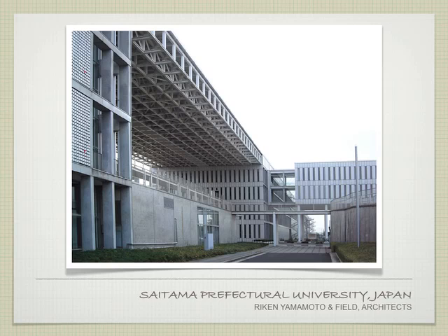right? Worcester Hall in Berkeley, the architecture building, which everybody thinks is ugly, is entirely made of precast elements like this would be. It's almost right on top of the Hayward Fault, so we have those same issues of how do we tie the building together. So the building itself is put together in this same kind of manner. Precast wall elements, right? Precast floors that have topping on them that kind of tie the whole system together, right?